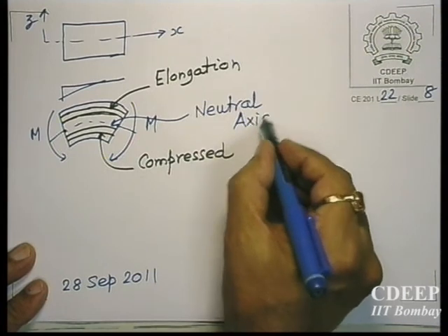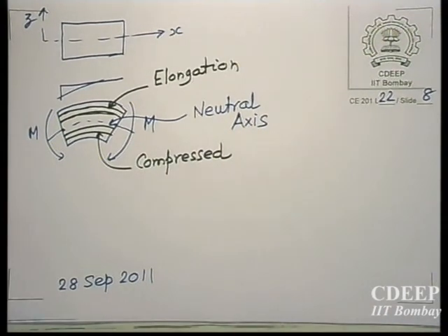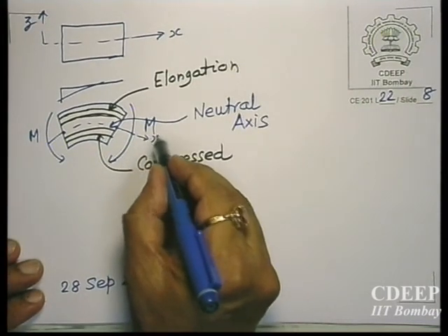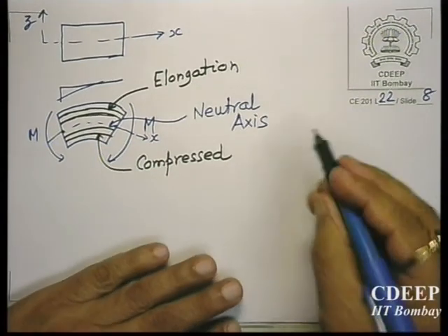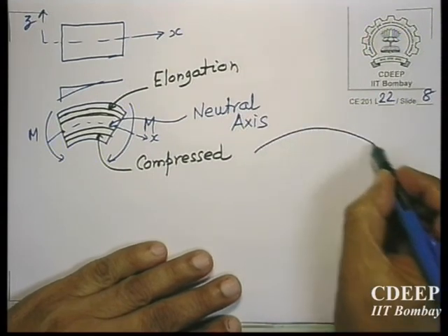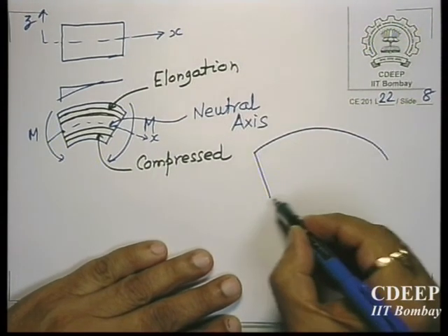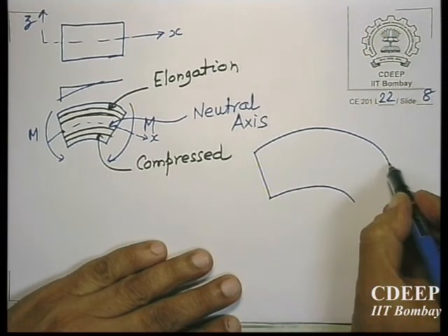So you have in the longitudinal direction one neutral axis. Your x-axis we always make coincident with the neutral axis. Whenever I draw, please take it that my x-axis is coincident with the neutral axis. So this is your x-axis, and once it gets compressed, can we not find out the longitudinal strain? That is very simple.